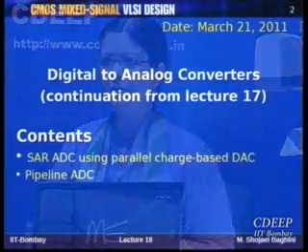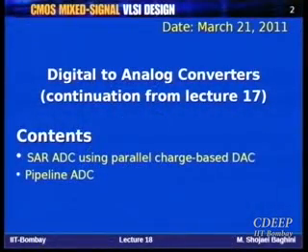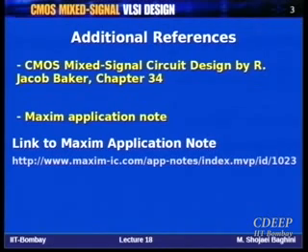Okay, so now we will continue by looking at ADC. Because now we have at least enough background knowledge about DAC, we will make ADC using DAC. First, looking at SAR ADC using parallel charge-based DAC, and then pipeline ADC. So I recommend using these two references for this lecture onwards when we are talking about ADC.